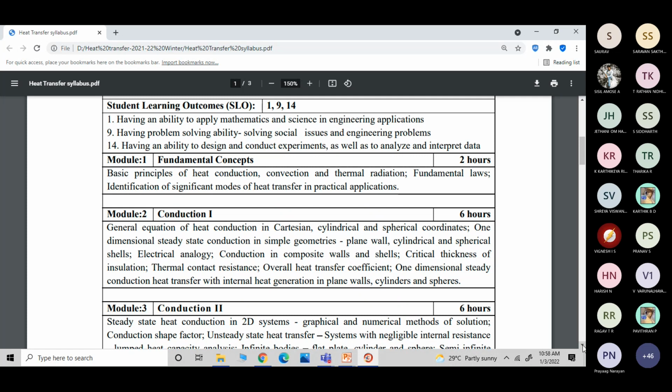Yes, sir. Okay, so for a pipe which carries hot steam, we have to properly insulate it. Otherwise, the temperature of the steam will reduce, and when the steam impinges on the turbine blades, the temperature will be lower, or there might be condensation also, right? If it gets condensed, it causes corrosion of the turbine blades. So to overcome that, we have to discuss composite cylinders, composite spheres, composite walls, etc. in conductive heat transfer.